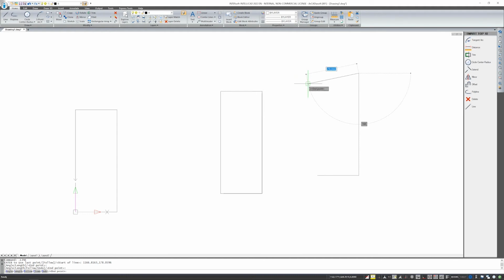Now we have such a situation that if we look at the angles non-relatively, then downwards is at 270. Whereas now you see that from this line that I last entered, this angle will be 180 degrees because I'm going to the left. Remember that the program shows angles ascending in the counterclockwise direction. And now, this is a good time to talk about the undo option.